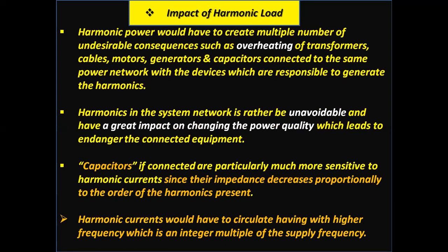Now, impact of harmonic load. Harmonic power creates a number of undesirable consequences such as overheating of transformers, cables, motors, generators, and capacitors connected to the same power network with the devices which are responsible for generating the harmonics.